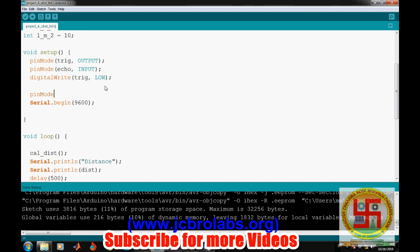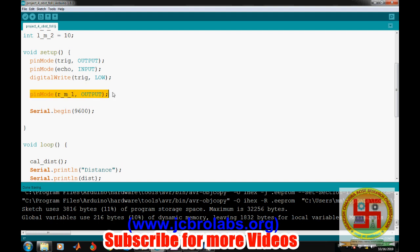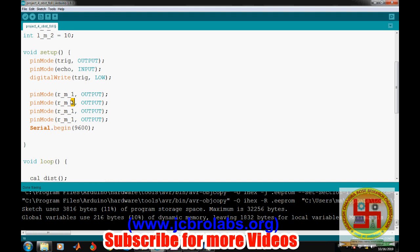So pin mode R underscore M underscore 1, that should be of output type. All these pins should be of output type, so let's copy it. And this is 2, and this is L, and this is L, and this is 2. So the initial state, let's make it 0. Okay, so we'll initialize all the motors with a stop condition.